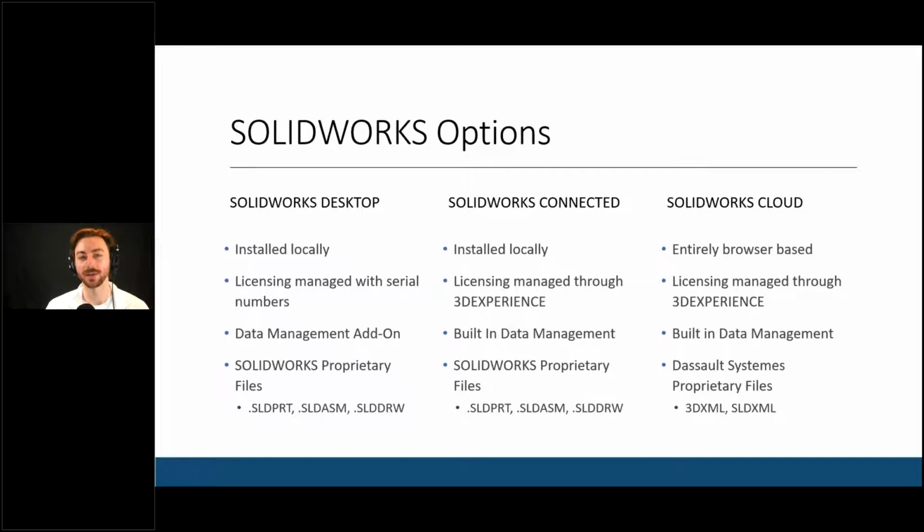you have an option to get connected to the data management tools and 3DEXPERIENCE platform with SOLIDWORKS Desktop. That is your SOLIDWORKS that's installed locally. That is the licensing still managed with that serial number. You deactivate it and reactivate it on another computer. Your data management is installed as an add-on, but your data file type is still your SOLIDWORKS proprietary files, SLDPRT, SLDASM, and so on and so forth.